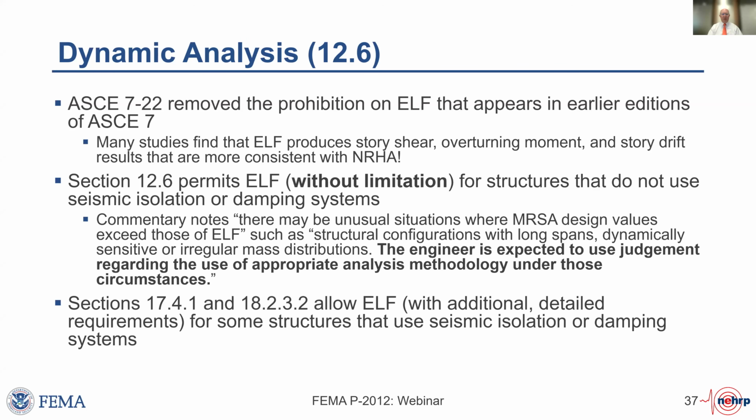And so we're allowed without limitation to use ELF unless we have seismic isolation or damping systems, and those systems allow ELF with some additional requirements. I again note the caveat, although modal response spectrum analysis is generally less conservative than ELF, it may be possible that there's some strange distribution, and so the commentary cheats a little bit and says you may still need to think about that modal response.